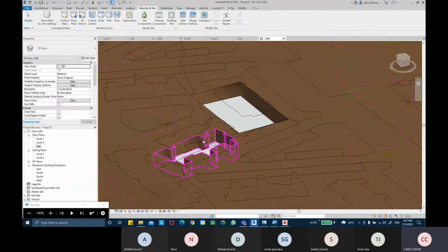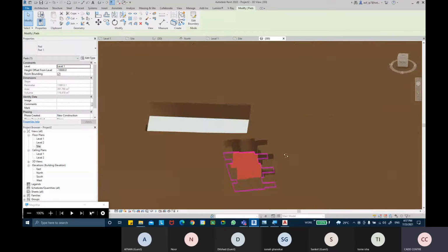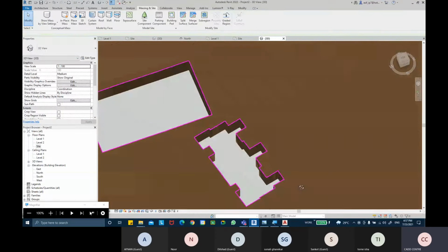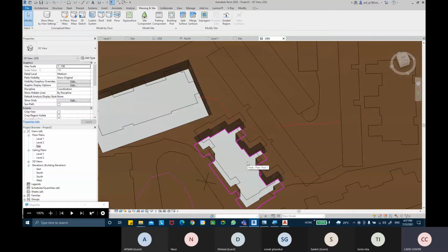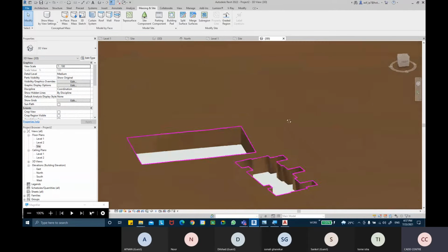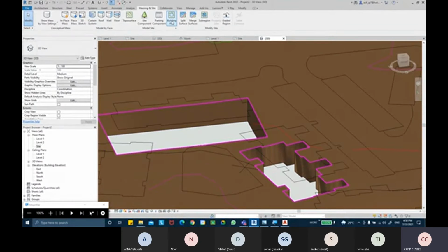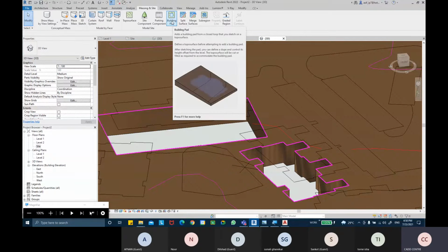So it would be going into negative 10 meters. So with the building pad, your foundation can lie on that flat ground, and you can have the columns and the beams inserted and your floors raised. So that's the building pad, to create a sketch on the topo surface to have a flat ground if you have an uneven ground surface.